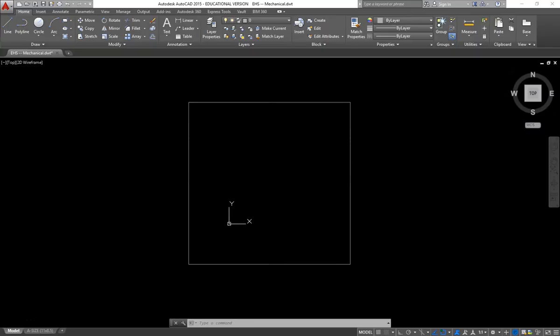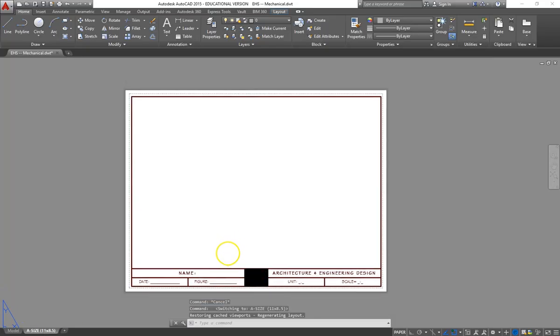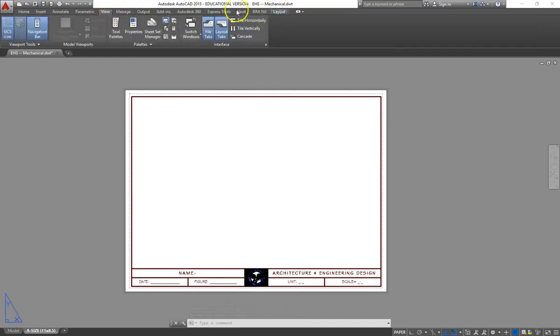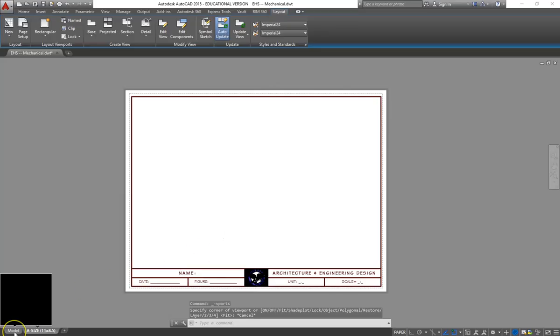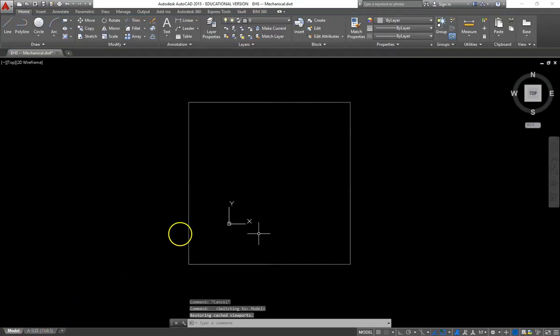In our previous unit, we learned how to scale a drawing by using the Zero layer, the View tab, Layout, Rectangular, and drawing a viewport box. In that unit, I gave you drawings which you scaled. In this unit, we will begin drawing objects and putting those drawings to scale on our A-size paper space.